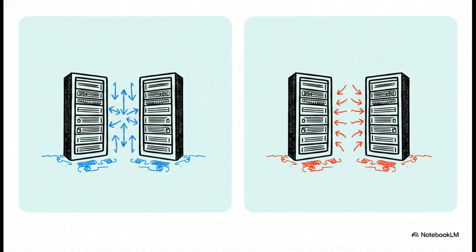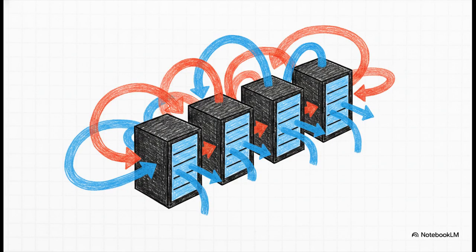Or, alternatively, you can flip them to create a hot aisle layout. This forms a dedicated corridor where all that hot exhaust is concentrated and pointed back toward the cooling system. But there is a huge flaw here. Air still mixes above and around the racks. These baseline layouts definitely improve airflow compared to just a random room of servers, but as well organized as it looks on a floor plan, it has a fatal flaw, because air is fluid. Without physical boundaries, hot and cold air simply travel right over the tops of the racks and around the sides to mix anyway. You're still losing efficiency because the separation just isn't absolute.